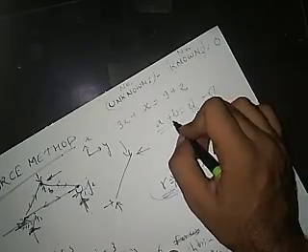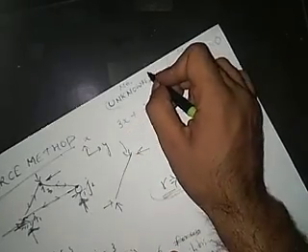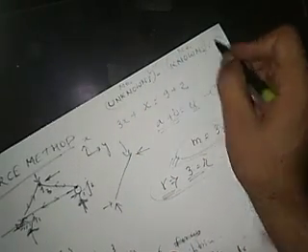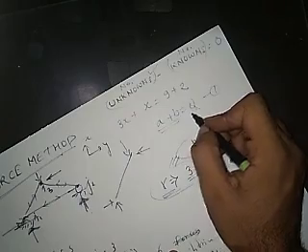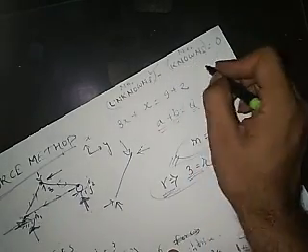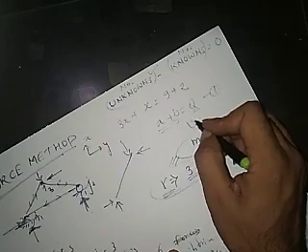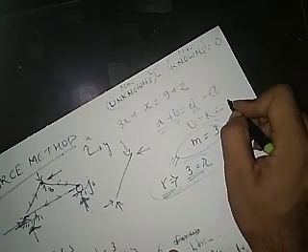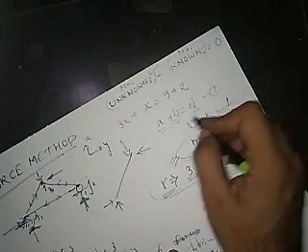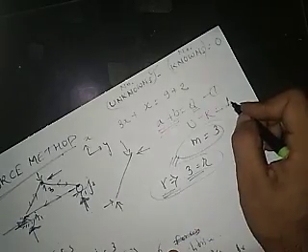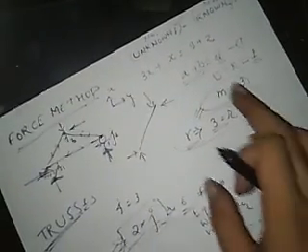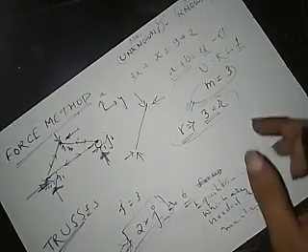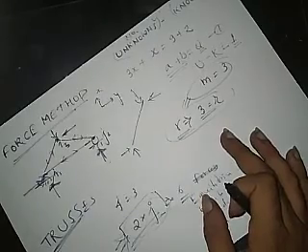So the number of unknowns is greater than the number of knowns. We'll need one more equation, and that is the case when unknowns minus knowns equals 1. This is called indeterminacy, the additional required equation. To get the answer, you need another equation, say a minus b equals something else, and then you can get the other variable.